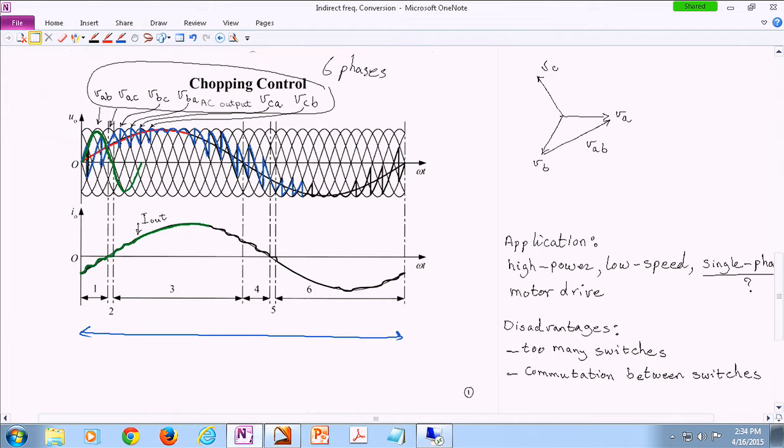Is it possible by creating more waveforms with lesser phase shift and having high frequency? More output waveforms? What do you mean by more output waveforms? More input waveforms. Oh, okay. Yes, as I said, if you use a phase shift transformer that physically generates some tricks, not only your VAB and VAC are there, we also have a 30 degrees phase shifter. So we have 12 of them in each cycle. So you have a better resolution, and therefore you can actually create a higher quality output signal, basically.